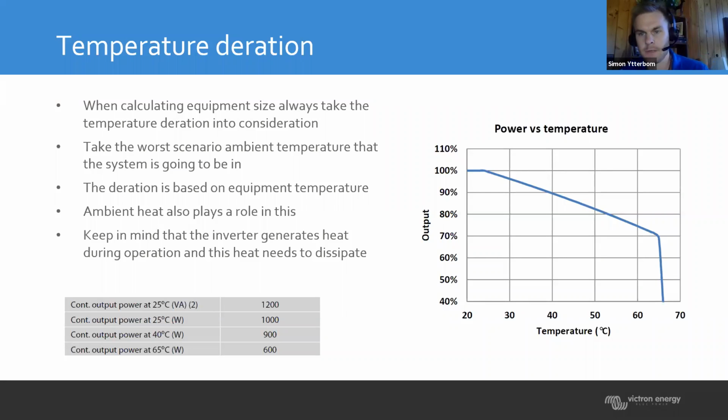So it's very important to allow for as much airflow as possible and try to keep the inverter in as cool a place as possible, to not only get the rated power out of it, but also to increase the lifespan of that inverter. If they're warmer, there are electronic components in there that will fail earlier than in a room temperature inverter.